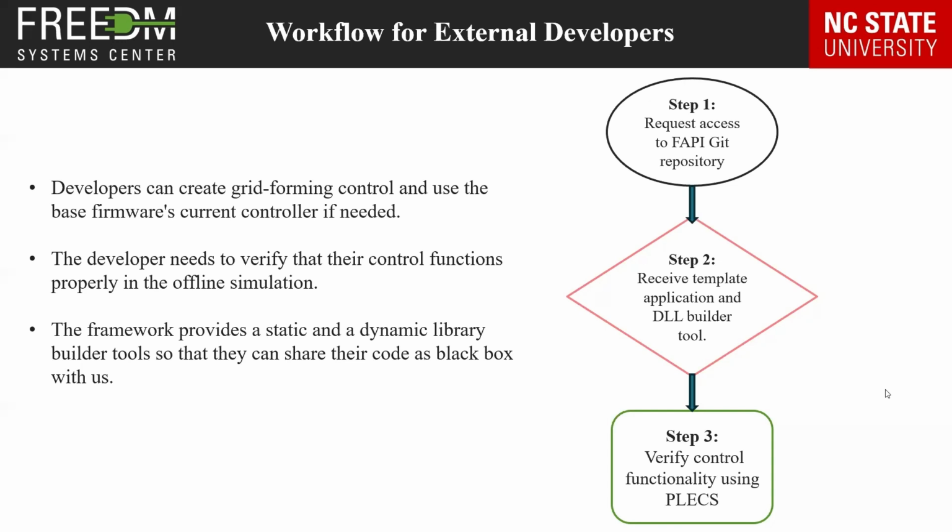Developers do not need to manage the DSP peripherals like ADC, PWM, or handle state machines, startup, shutdown. These functionalities are managed by the FAPI framework code, which resides in either the DLL file for the SIL or the static library for the C-HIL or the hardware development environment.